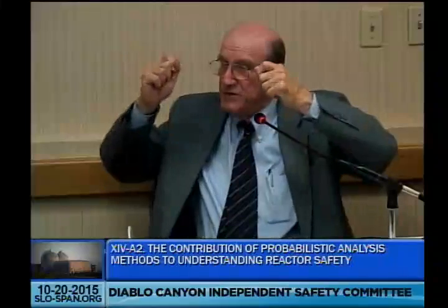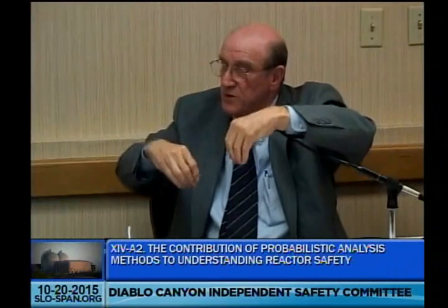So when everything else is done, you have to show that too, and there are about a dozen of them. For example, one of them stipulates that you need to shut the reactor down, but for some reason, not stipulated, the control rods don't go in. So it's called a transient without scram. In other words, a transient in which you can't put the control rods in, and therefore you can't shut down the chain reaction the normal way. The reactor must be designed with other systems and other functions to safely keep the core cool and radioactivity contained in the event of one of those. That's another one of the stylized accidents.